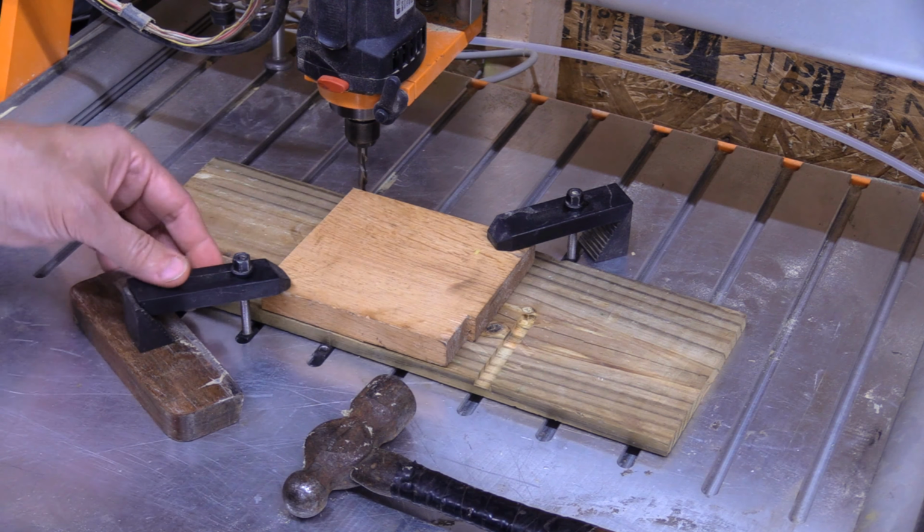All right, now I got this block held down nicely. Hang my wrench back up. All right, let's go away from this piece of wood, back up here. All right, now I'm going to set my X coordinate. All right, back down. Move this over. And I know this piece is cut 90 degrees. This is a good cut off the table saw, so I'm just going to come over until this just touches. That's good right there, and I'm going to hit my X0 right there. Okay.